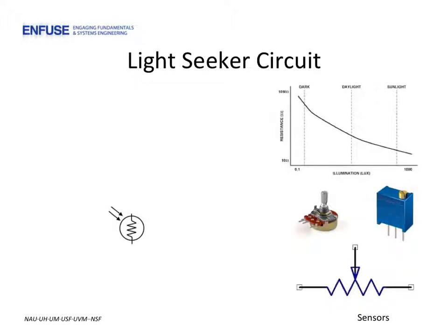Earlier in this module, we discussed the use of a light sensor to either seek or avoid bright light. Let's consider how we might develop circuits to do these tasks. Our first circuit will consider the case of responding to low light. An example could be a sensor used to track a solar panel, or one to simply turn on a light when it gets too dark. Let's consider the latter, for which we can utilize the same voltage divider setup as we discussed with the thermistor.